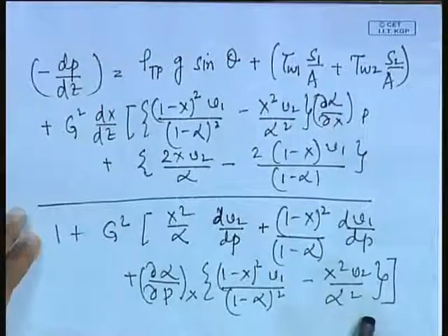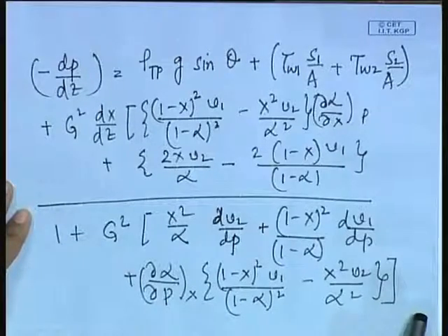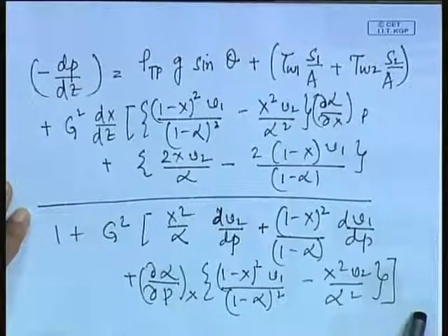and then you will find that this will in no way guarantee us the condition of compound choking. In the next class, what I plan to do is, first I will be deriving the condition of choking from this particular denominator, the denominator which I have written down here. If you see what I have written down in the written matter, you will find that from this denominator, equating this to 1 minus Ma square, we will be getting a condition of choking.